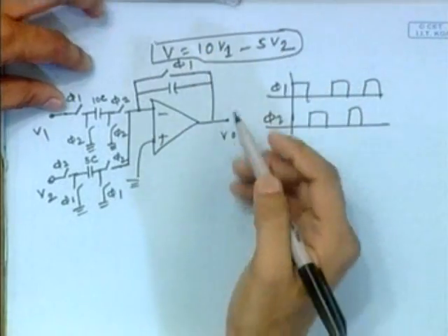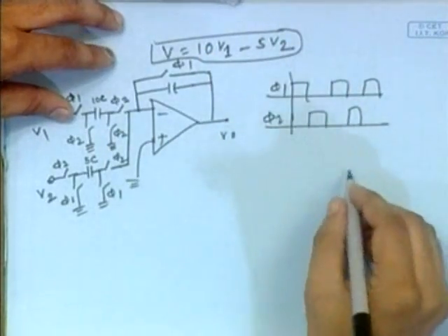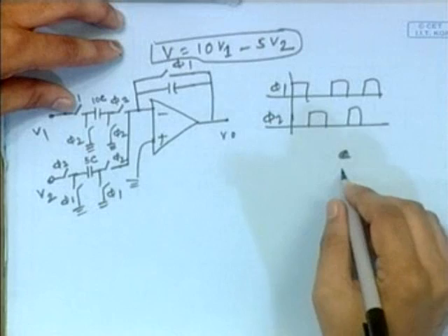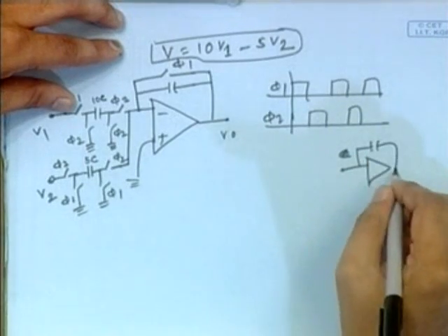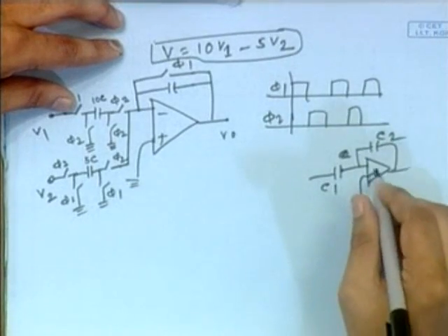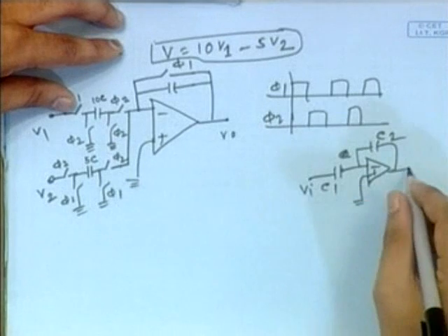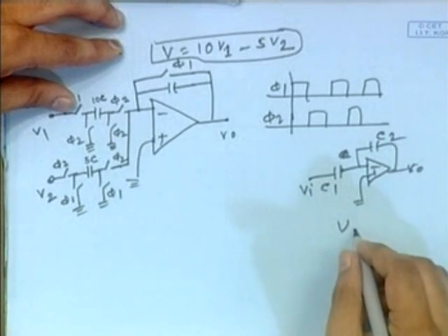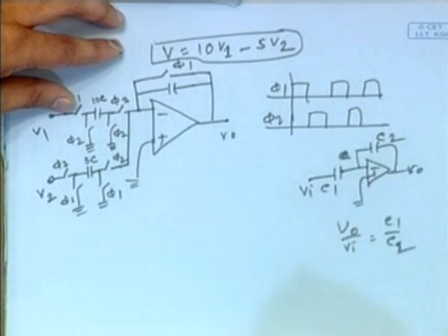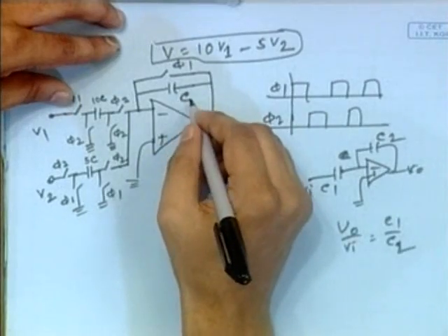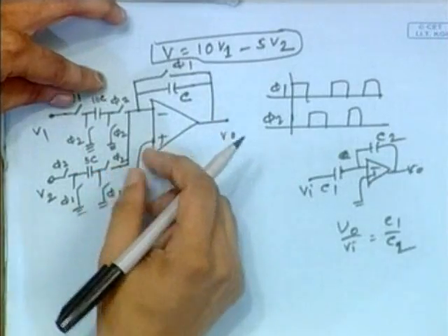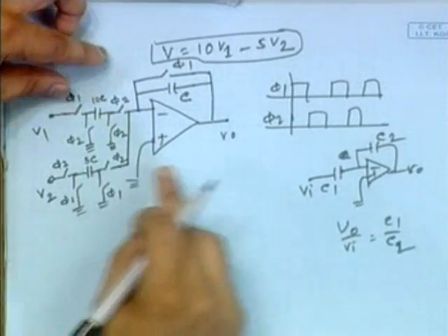Now we have got that for the switch capacitor amplifier, the voltage gain, suppose this is equal to C2 and this is equal to C1. So voltage gain V out by Vi is equal to C1 by C2. So suppose this is C, you are maintaining the ratio only, C by 10C, C by this one. This is 5C. Now what is happening?